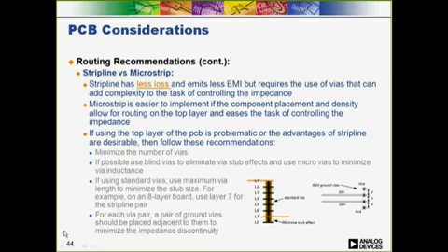The pin assignments for our devices are made such that routing on the top layer is possible. The FPGA JESD204B pins should likewise be assigned to make this routing feasible. If it's not feasible to use the top layer exclusively for routing the differential pairs, we do have some recommendations regarding the vias.